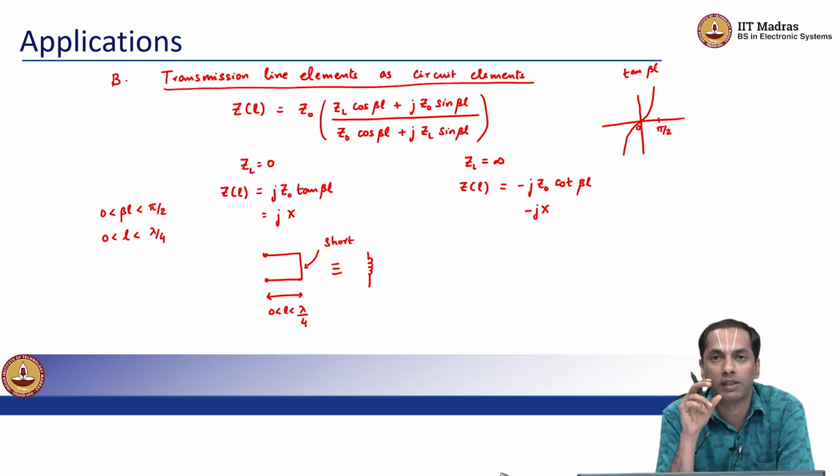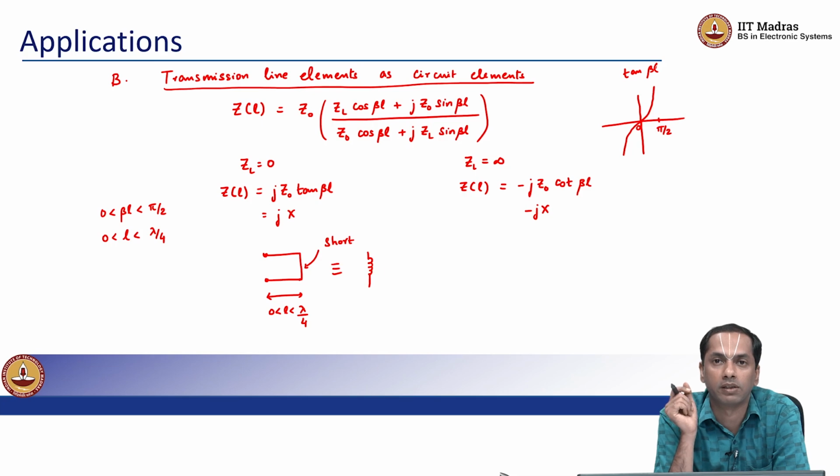So I can incorporate these tiny lengths of transmission lines, between 0 and λ/4 with a short circuit at the end of it, wherever I need to have an inductor of certain value. This will of course again be very frequency sensitive. I can only guarantee you that the value of this inductance will be what you want at a very specific frequency, because remember, this is fundamentally dependent on the constructive and destructive interference behaviors, which is a frequency dependent phenomenon.